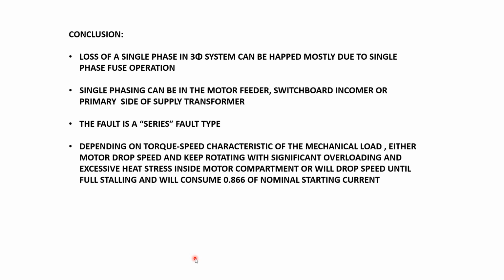And then, depending on the torque speed characteristics of the mechanical load, either the motor drops speed and keeps rotating with significant overloading and excessive heat stress inside the motor, or it will drop speed until full stalling and will consume 0.866 of the nominal starting current.